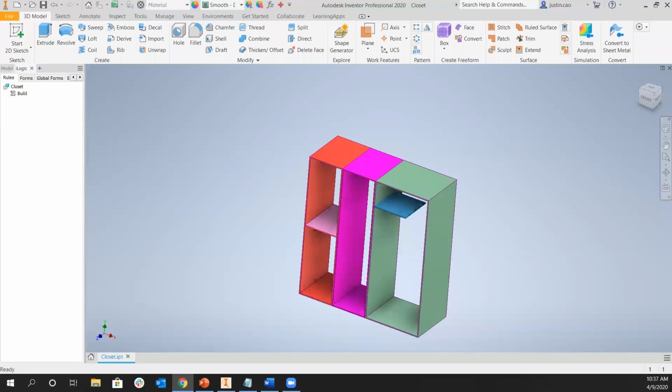So from Edward, best practices for configurable models, assemblies. Best thing to do, let me go ahead and answer that live, is make sure that you're driving everything off of a specific point. You don't want your model jumping around from quadrant 1 to quadrant 2, quadrant 3, quadrant 4. What I like to do is build everything based off the origin and then constrain off the origin. So when you start placing these into assemblies using the Inventor API, the model doesn't end up in a weird location.